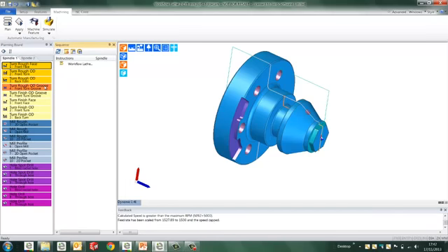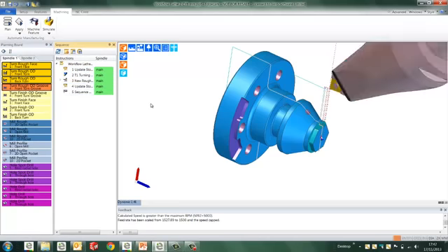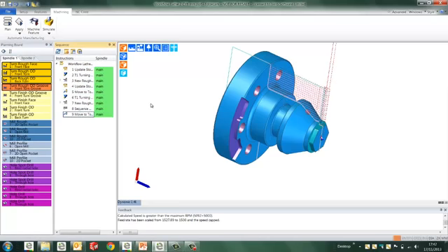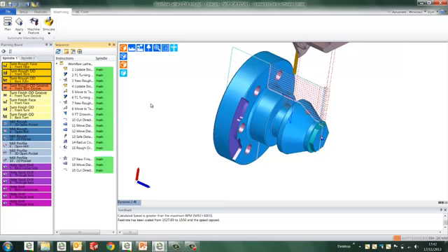There's several ways we can do this. I can execute everything with one button click, but here what I'm doing is executing the rough turning as a group of 4 machining toolpaths. So first of all we'll rough the face, then we'll turn the OD before machining the groove.